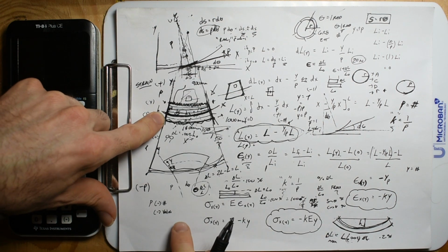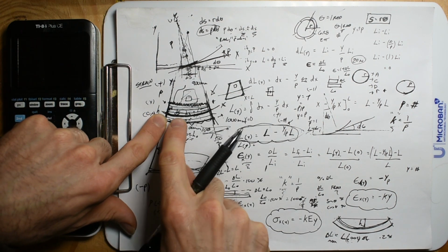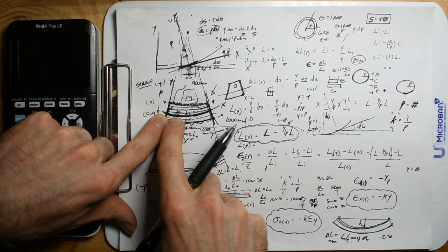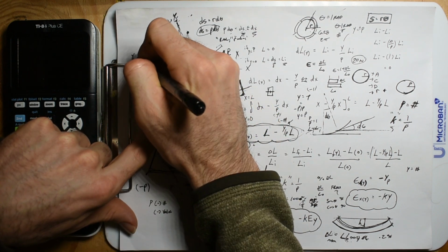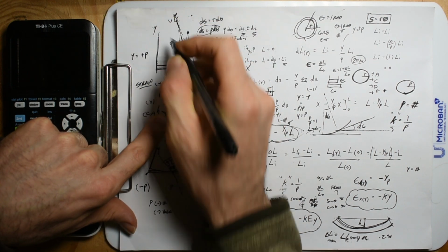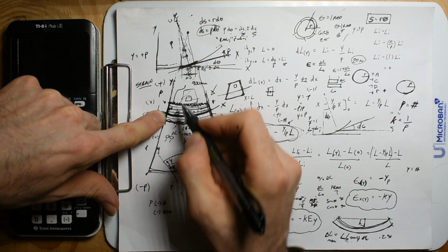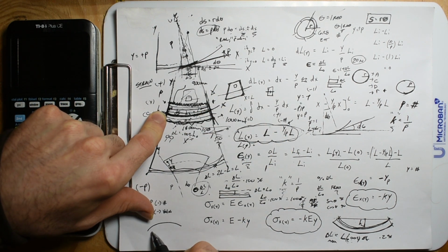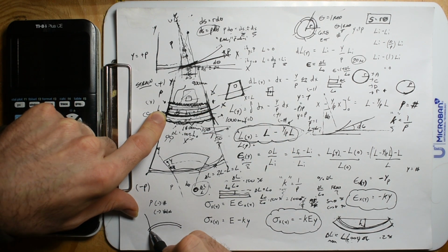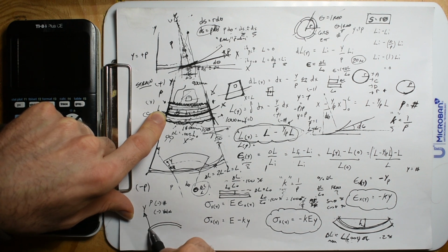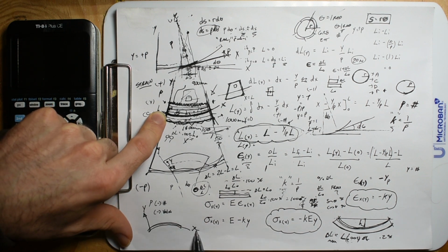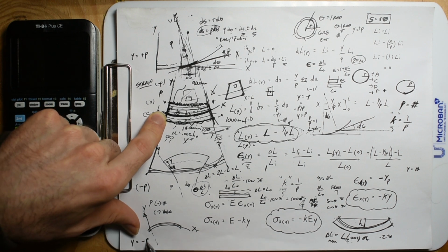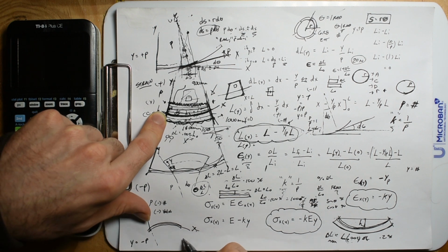And one reason you can see this is, hey, my y value is going to be a positive rho. If I did a curvature like this of a beam, I'm still going to put the up direction as my y-axis, and this is my x-axis. But guess what? The radius is negative, so y would be a negative rho.